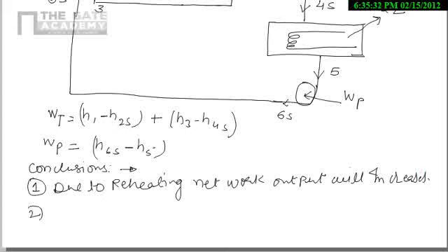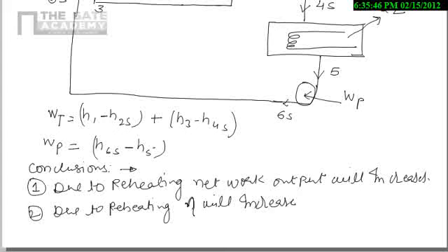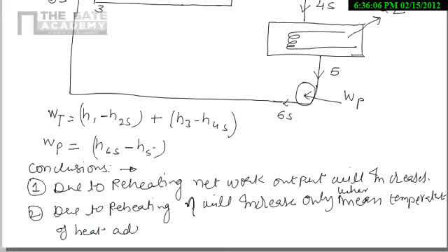Second, due to reheating, efficiency will increase only when the mean temperature of heat addition will increase.